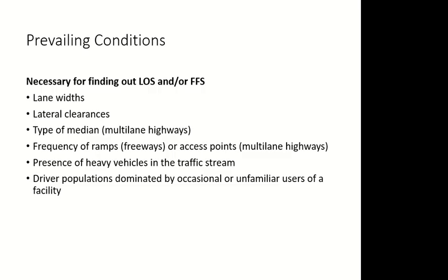But let's say you did not get a chance to do the spot speed study in the field, so free flow speed from the field is not available. Then I have to do some calculations to find out the free flow speed. For these calculations, I need these extra values from the field. Otherwise, we don't need them.